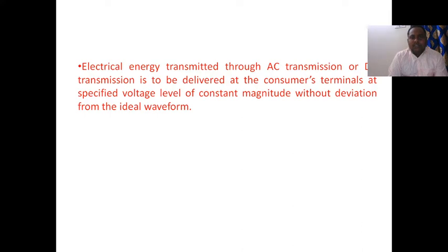For eliminating these harmonics, we use DC smoothing reactors. Already I told that smoothing reactors serve two purposes. The first one is that they eliminate the harmonics. A smoothing reactor is nothing but a large inductance. We know that an inductance does not allow a sudden change in current. The smoothing reactor also protects the circuit from over currents.